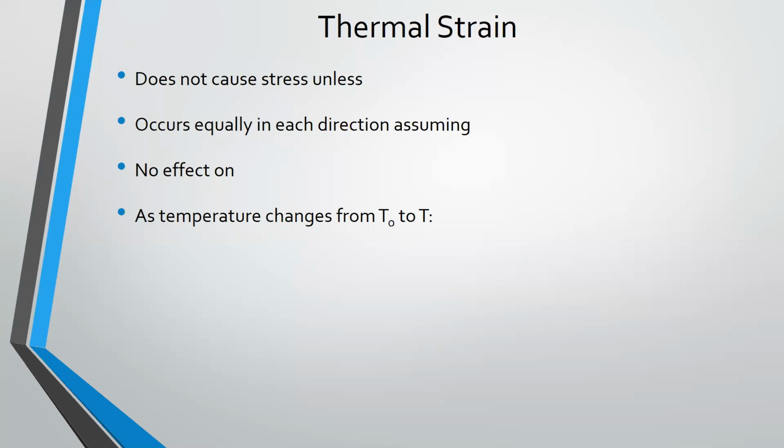And more accurately, what it does is when cracking occurs due to expansion, or probably more likely due to contraction, it gives a weak plane where it guides that crack. That cross-section of the concrete is thinner there than anywhere else, so it tends to guide a crack to occur at that location, and then you don't see it because it's inside of that divot. It doesn't always work. You've also walked on sidewalks where you see cracks, and that's because they've heated up and then they've tried to cool, and that material is pulling away from each other, and that's where it let go.